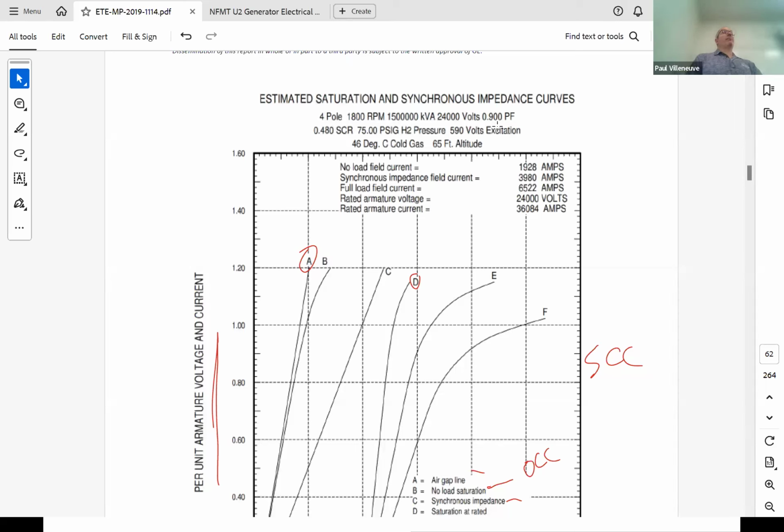So if you wanted to run it at 0.85, leading or lagging, it's not going to work, or it's not guaranteed to work. And that's why our friends in the utilities say, hey, if your power factor at your site is really bad, you're going to pay more money, because we have to do a lot on our system to make that work. Most generators are designed to operate at 0.9 leading or lagging. Some of the cheaper ones are designed to go to 0.95, but it just depends on the utility.